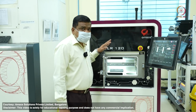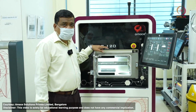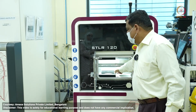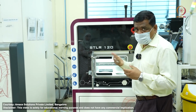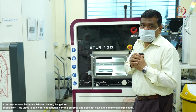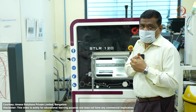This is another new machine which is being manufactured at MS System. It is the STLR 120 model. Essentially, this is the build plate, and this is a single laser system. The maximum build volume that can be printed in this particular machine is cylindrical in shape, with a 120 millimeter diameter and a maximum cylinder height of 200 millimeter.